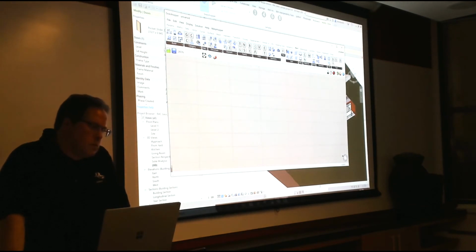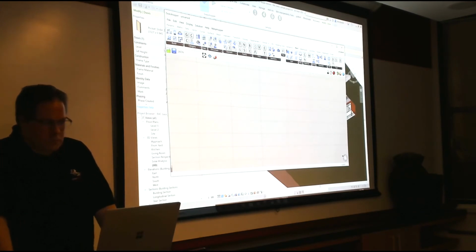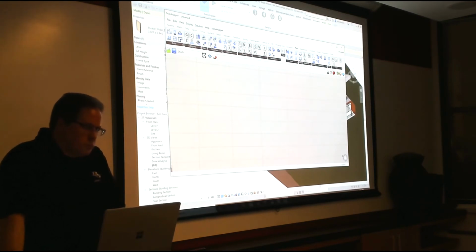Yeah. So, is there a push to get that to all kind of seamlessly work? I can get it to work with two different scripts, essentially. Say I have geometry that defines an adaptive component family, however we want to define it geometrically. I need a separate script that does that parametrically, then save, close, push it out to Revit, and open up another Grasshopper script that defines the points for that adaptive component family to generate. That's right. Yeah, that's how Revit works.